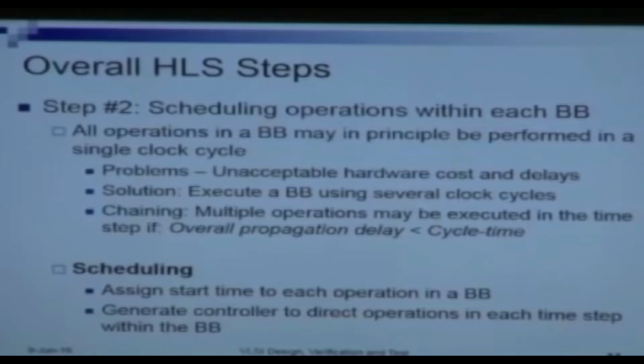So likewise, for all different types of operations, all have to be given separate operators or functional units to execute, and therefore it will lead to unacceptable hardware costs because of the reduced resource sharing. When we divide things into different time steps, I can share the same resource at different time steps, which is not possible if I do it within a single clock step. And also, it will increase delay.